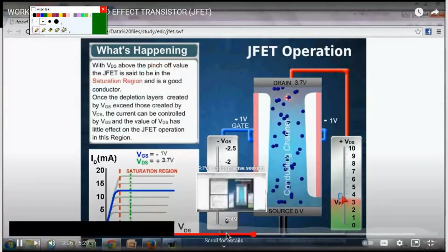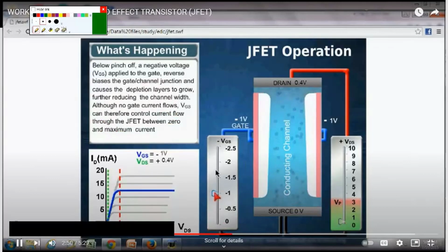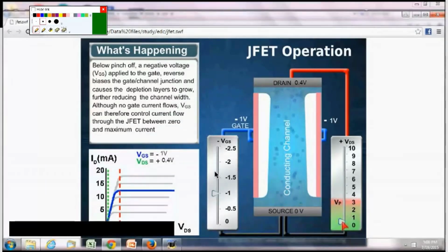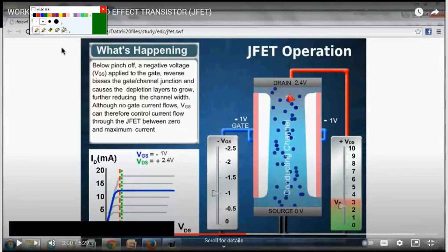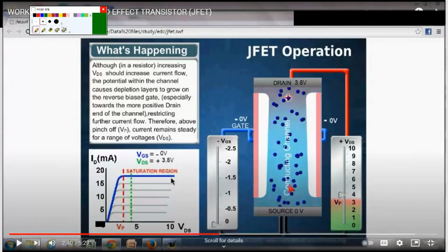Here we start to control based on VGS. Here is VB, so I will add negative volts, and we'll keep VDS at 0. So let's say I keep VGS at -1 volt, adding more and more reverse voltage, so the channel closes more and more. Further, if we increase the VDS, we can see that current also increases, but again it is smaller. See the graph here. Focus on this output.